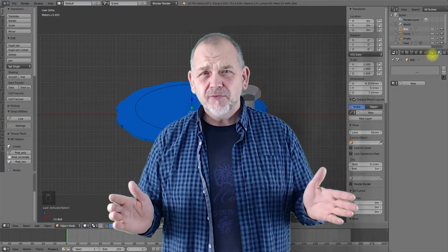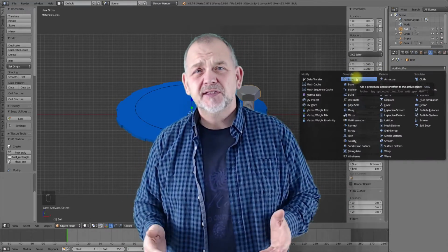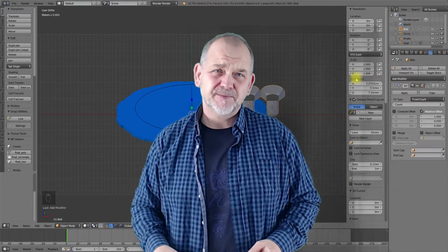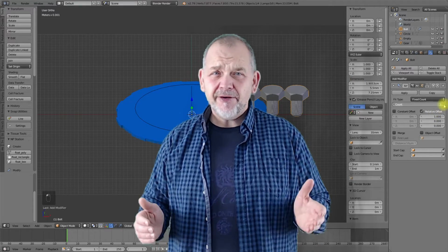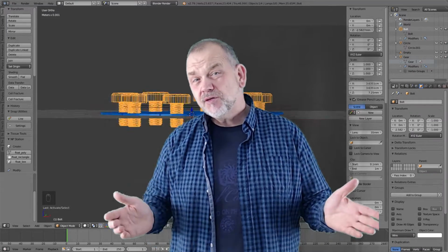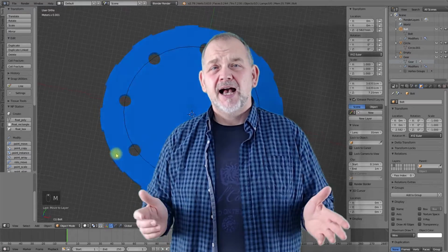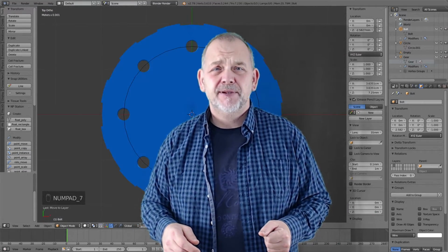You can overcome the limitations of Blender using the introduced techniques that I have shown to you during the past episodes. For example, the use of the numerical input, the direct use of global or sometimes local coordinates, the use of the 3D cursor, the measuring functions, as well as the proper application of the Blender object